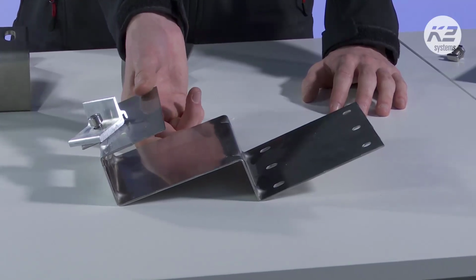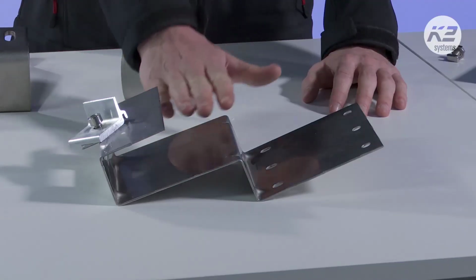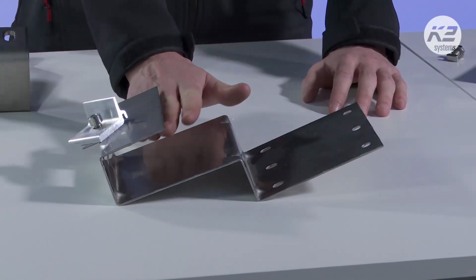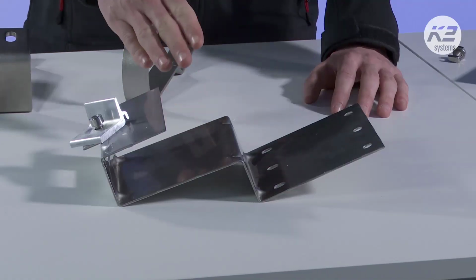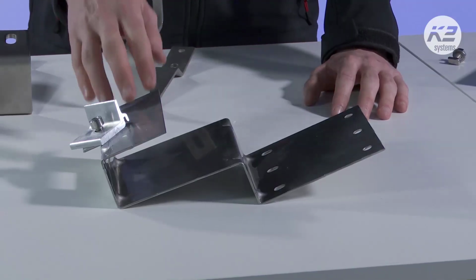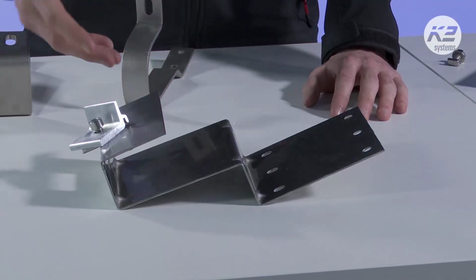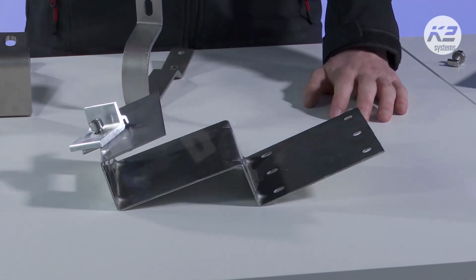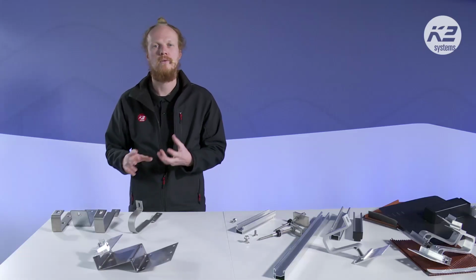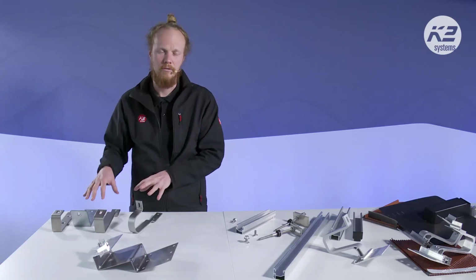And this is what he was talking about, where if this material is going to rest onto the tile underneath, the tile has to be strong enough to withstand this force. And so for this reason, we only use this with concrete tiles. Clay tiles have the potential to crack. With most other, or almost all other roof hooks that we have, all of the weight is distributed into the hook itself.